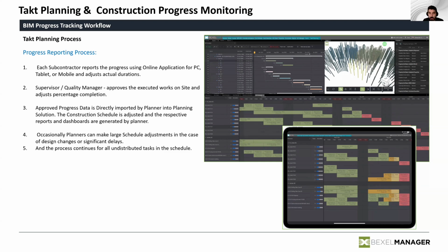So let's say if I have 2 drilling machines and I have to complete this area in a week, I could simply assign them specific piles that need to be driven, to specify the sequence, to specify the hours needed for work, instead of just saying to them, okay, there is a task, subzone 4C in zone 4 that needs to be executed. You have 1 week, you have two pile drivers, just go ahead, because that's simply not detailed enough for the needs of a construction site.